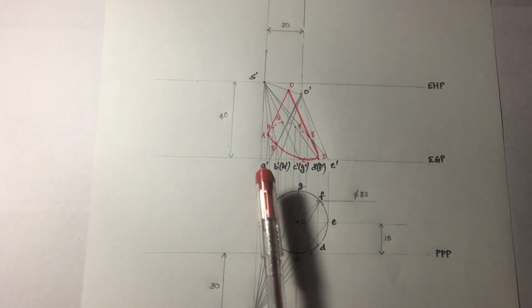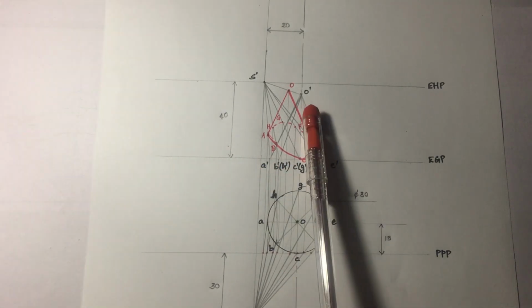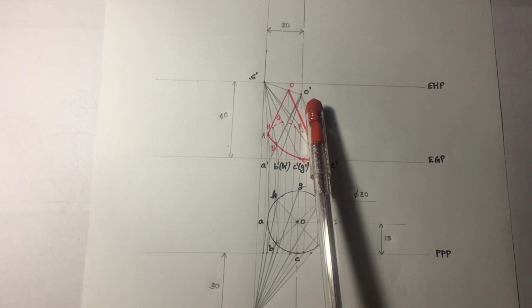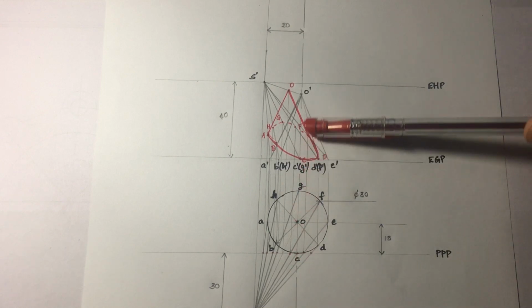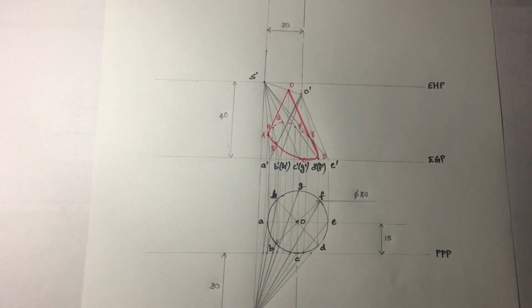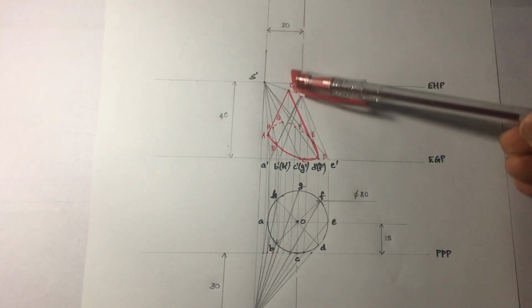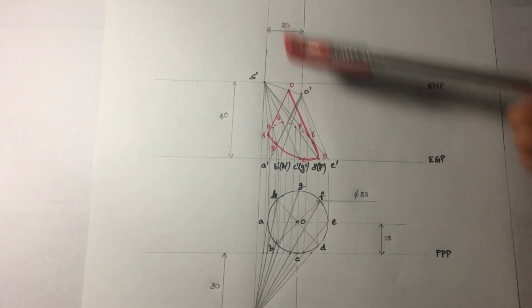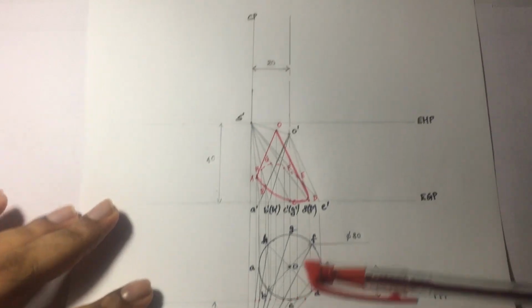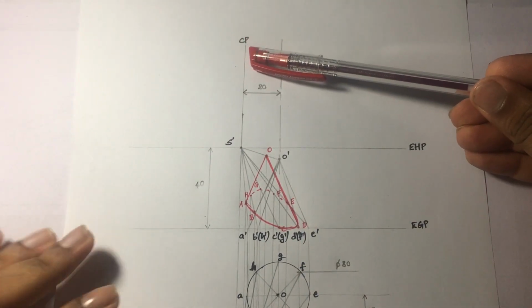And you will be getting 5 points in the EGP line, and you will be getting a central axis point as O dash. Through the central line, you have to draw the axis by using chain lines. After doing this much, the very next step is to draw the central plane. And it is told in the question that the central plane is towards the left of the axis of the cone. So from this axis line, you have to take 20 mm towards the left of the axis, and you have to draw a perpendicular line and name that point as CP, which represents central plane.